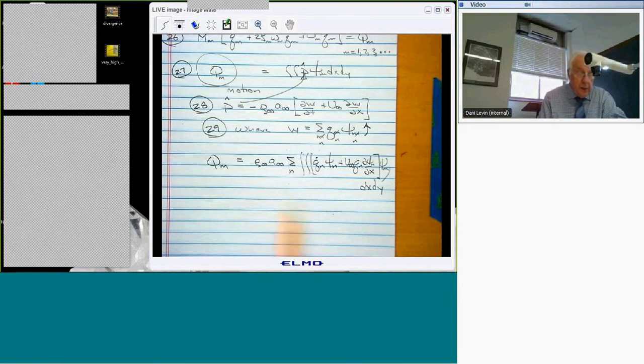So the point is that in the nth mode generalized force, there are a lot of terms. They're all in whatever the total number of modes I have. All of those modes contribute to the aerodynamic pressure, and of course the aerodynamic pressure contributes to every generalized force for each of the structural equations of motion. Okay, so those are the equations.